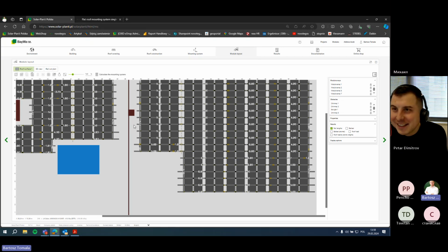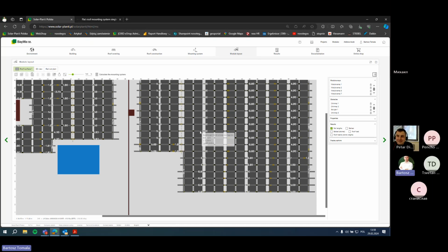Okay. So here the maximum length of the rails combined together, fixed combined, will be a maximum of 3 rails. So it will be about 17-18 meters. And after this, you have to make this expansion joint, and then you can combine, let's say, 3 rails together.